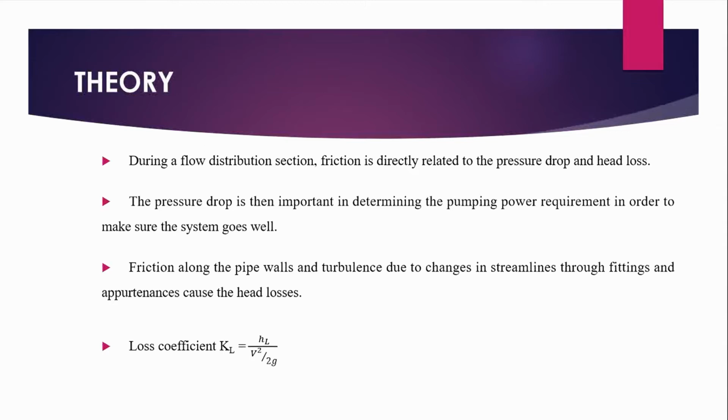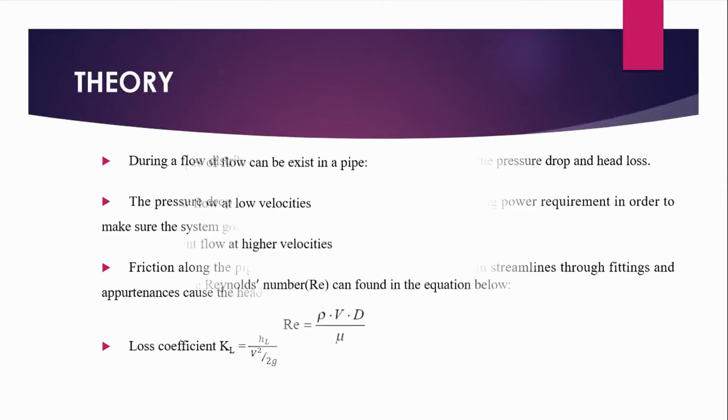Various joining components such as fittings, valves, bends, elbows, tees are involved in a typical piping system. Loss coefficient is usually used in minor loss expression as shown in the slide, where HL is additional irreversible head loss in the piping system due to the insertion of the components.